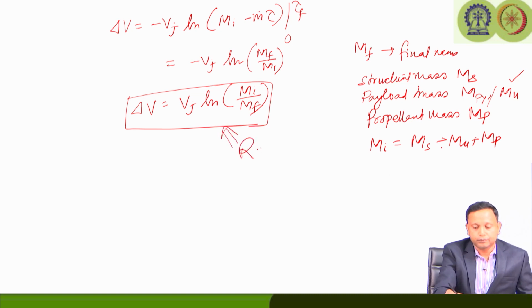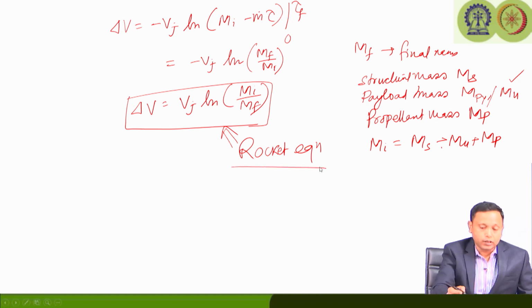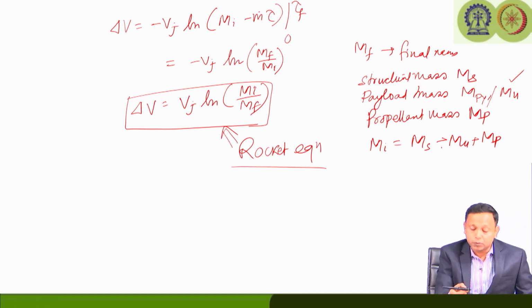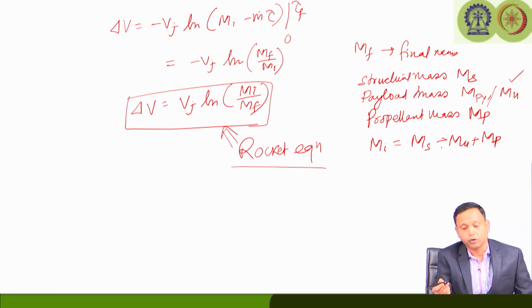the rocket equation, which was derived by Konstantin Tsiolkovsky. So, sometimes it is known as Tsiolkovsky's equation as well. This is a very important equation because it tells us that the ideal velocity increment is related to the efflux velocity or jet velocity Vj and the initial mass and final mass of the rocket. And this is irrespective of the mode of ejection we are talking about, be it a liquid rocket or solid rocket, it does not matter. This equation is equally valid.